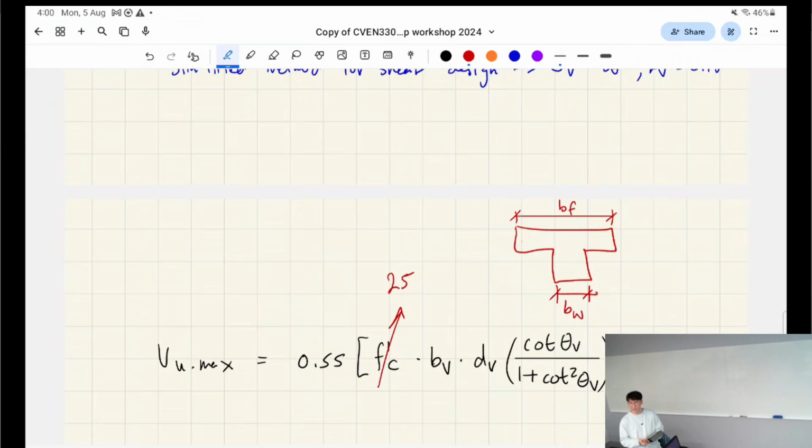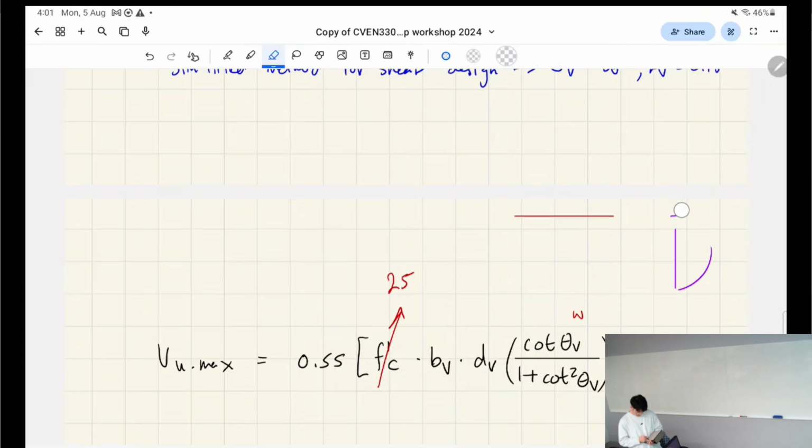If you've done solid mechanics or steels, this might ring a bell. So, okay, basically, here's what the shear distribution will look like. You don't really need to know this, right? So this is the shear stresses, right? If we map it to the depth, we have way more shear stresses when the width is smaller, right? The smaller the width, the greater the shear stresses, right? So if any part's going to fail, it's going to be this part in shear, okay? It's going to be the area of less width, I guess you can say.